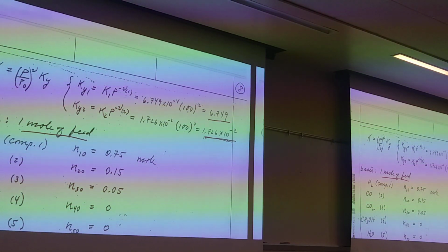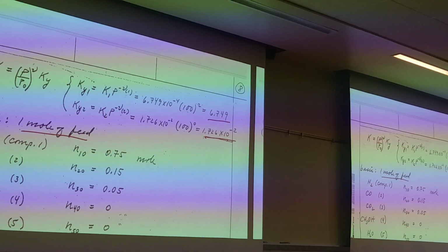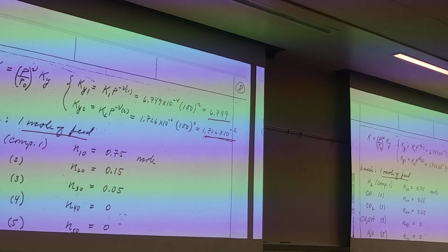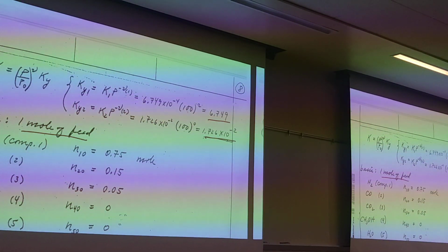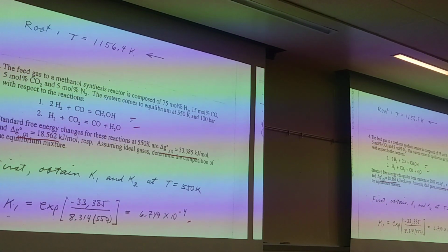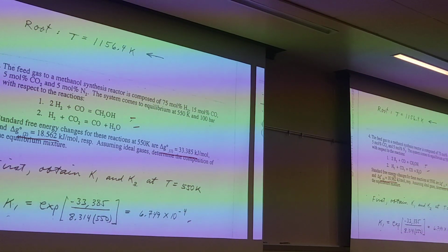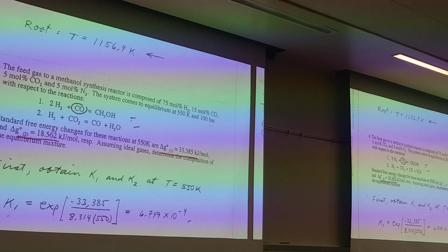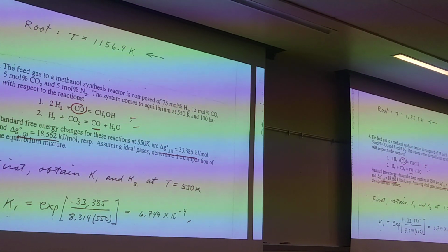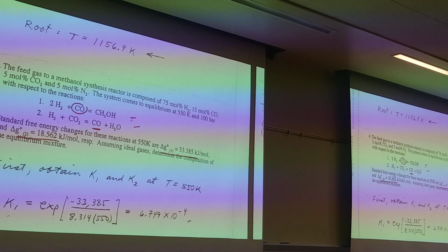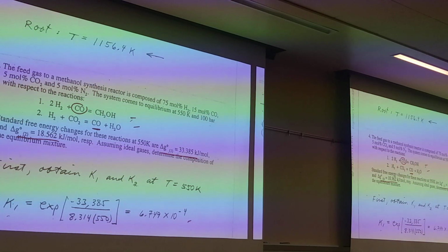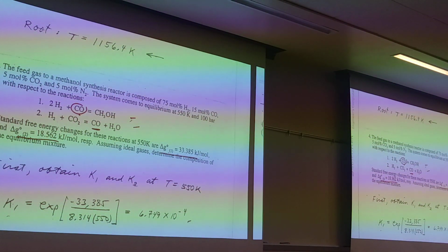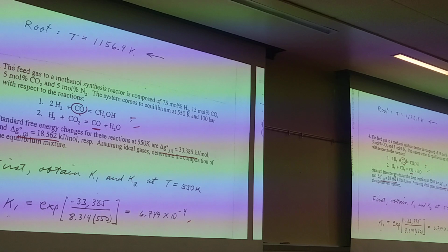Do you mind explaining again why the upper limit of Xi1 rises to 0.2? Yeah, let's look at the reactions here. Here, this is my limiting reactant. But you see that I can produce some of it here in the second reaction, so I have to look at the maximum that might be produced in the second reaction and add it to the initial inventory. The first one, yeah.